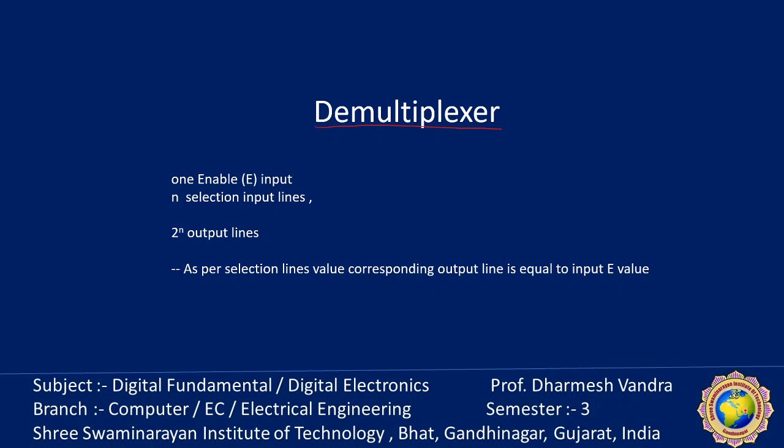Most, if not all, IC decoders include one or more enable inputs to control the circuit operation. Enable means that if the circuit input is enabled, then it works according to its functionality. Otherwise, the circuit is disabled and the output is not according to the definition. Remember that all outputs are equal to 1 if enable is 1, regardless of the values of inputs A and B. When the enable input is 0, the circuit operates as a decoder with complement output. Now, the demultiplexer has a standard enable input.